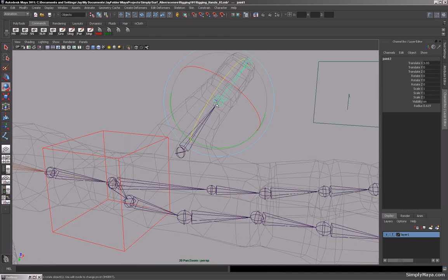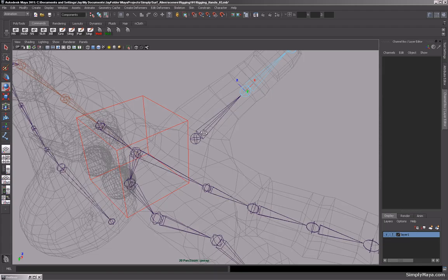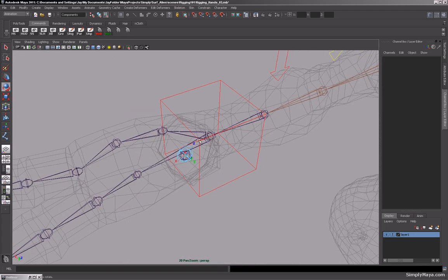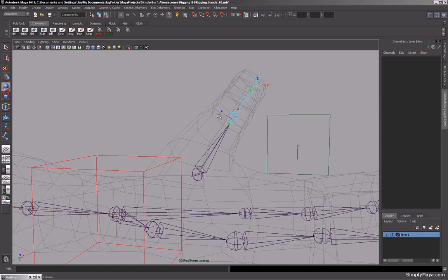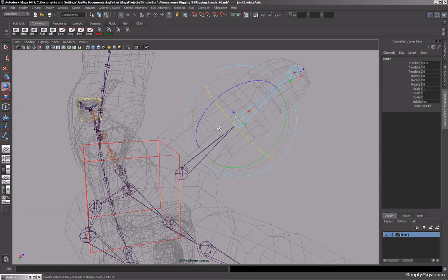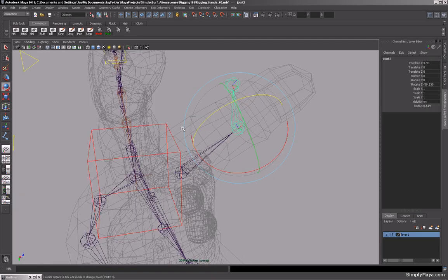And also what you'll need to do is the same sort of thing with the joint here. You may need to just tweak that joint axis or the orientation of the joint just so it matches exactly with the angle of the thumb itself. So for me that would be about there, and then hopefully if we go back to F8, that's going to bend fairly well.